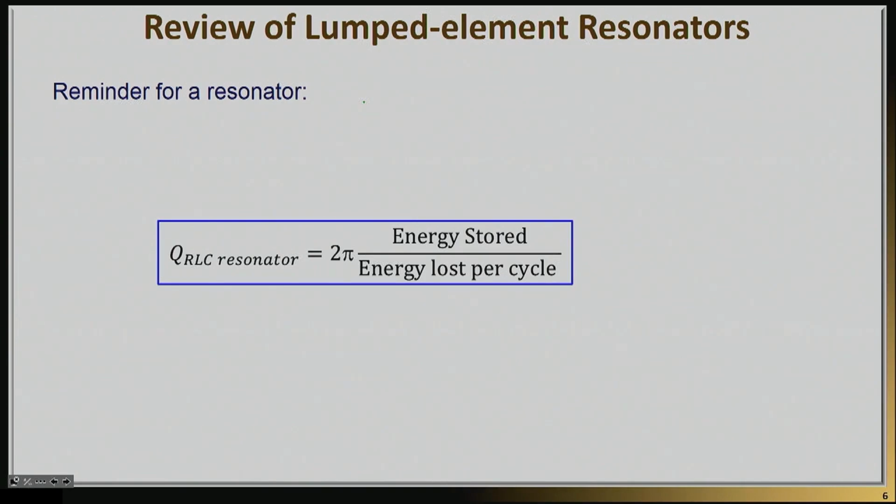So the quality factor, Q, is a very general quantity that is essentially defined as practically the energy that you can store in the resonator versus the power that you have to lose per cycle. Ideally, this quality factor should be as high as possible. So ideally, we're looking for lumped element resonators to have quality factors as high as possible. Of course, infinity is a great number, but it doesn't occur in real life. But high Q is good Q.